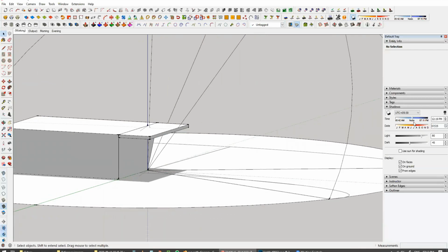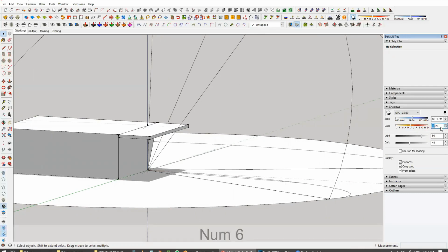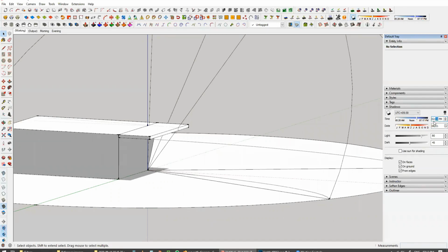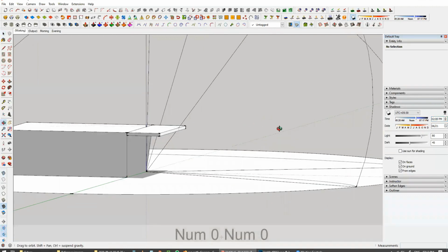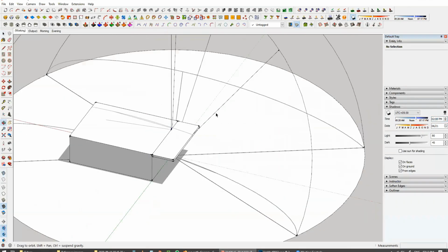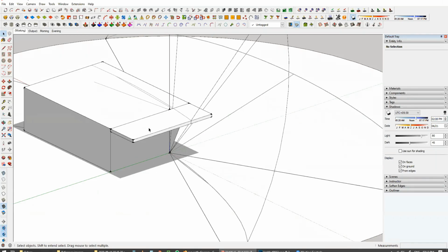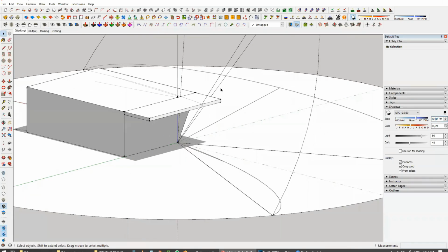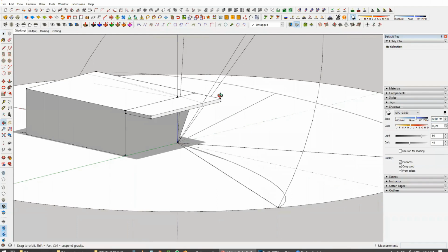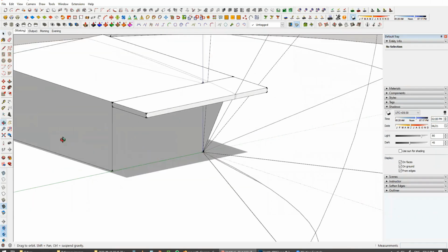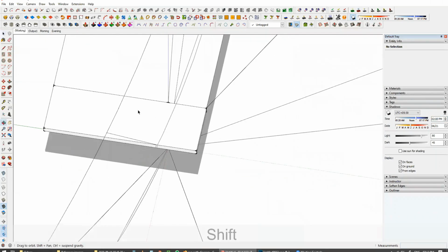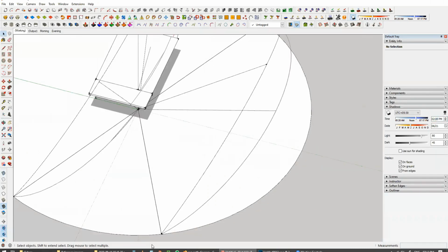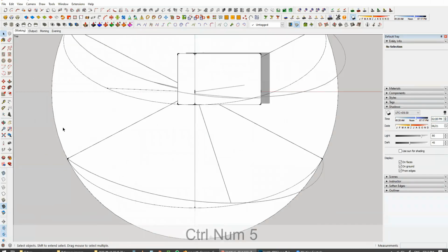So if I change the time, and let's say at around 2 o'clock, we're designing it for 2 o'clock. Okay, so if the sun is coming at 2 o'clock from this direction, then this projection will prevent the vertical sun, and if you want to prevent the horizontal sun, you can also use the same technique if it is coming at an angle in plan direction.